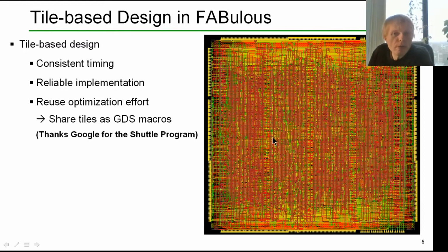They build an ecosystem also around open source PDKs, and that allows us to basically share GDS macros, and that means that using, for example, the SkyWater 130 nanometer process, it will allow you to implement FPGA fabrics just from such pre-compiled macros, rather than going all the way to tiny standard cell elements. So that makes life very, very easy. It's a big advantage.